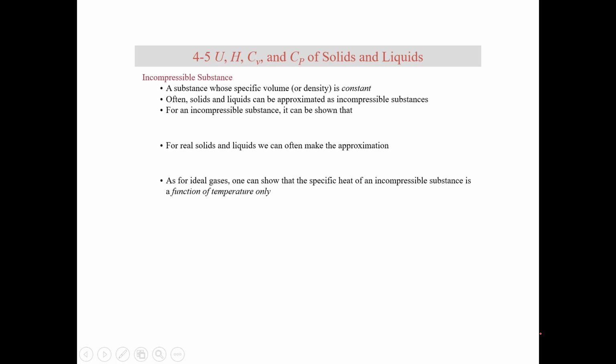Okay, we're going to now progress to looking at internal energy, enthalpy, and specific heats of solids and liquids. Let's look at an incompressible substance. A substance whose specific volume or density is constant is an incompressible substance. And often, solids and liquids can be approximated as incompressible substances.